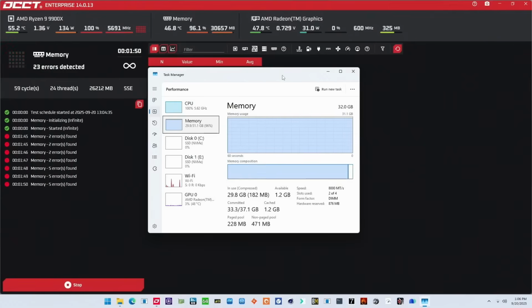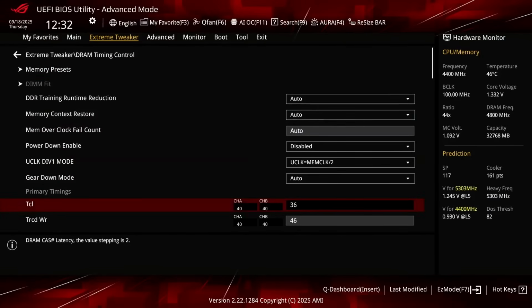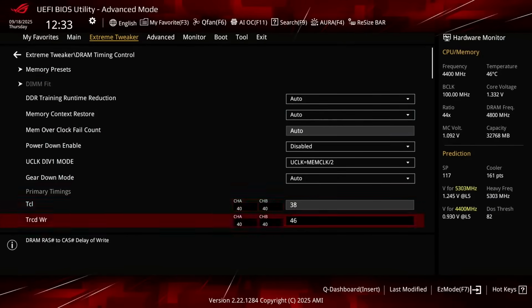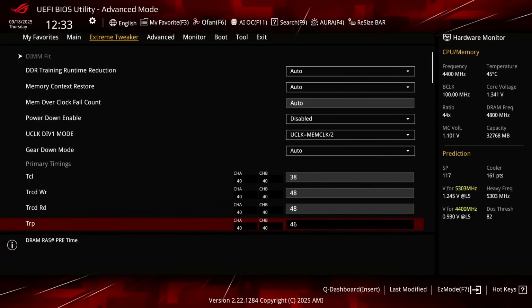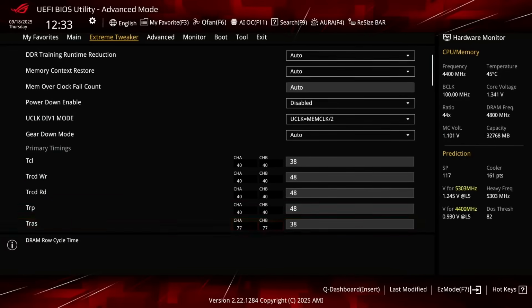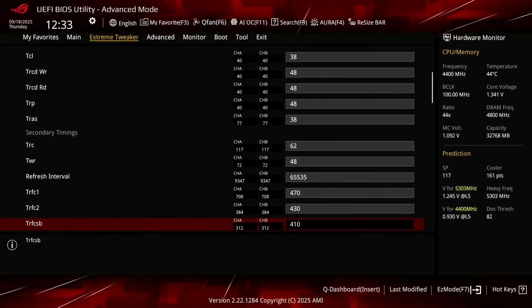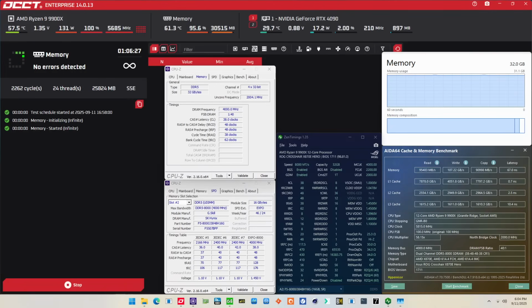But no cause for alarm, because we've seen this in previous overclocking guides as well. To fine-tune the timings, I try setting certain timings back to its EXPO value until I find the timings that caused the errors. Unfortunately, unlike with previous overclocking guides, I had to adjust quite a lot more timings to make the memory pass our target of 1 hour of OCCT stress testing.